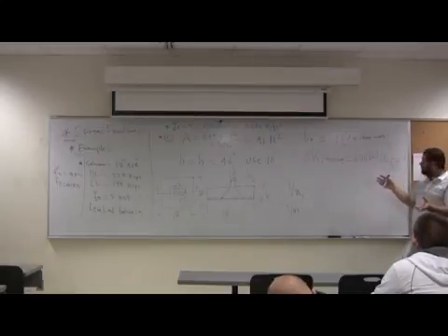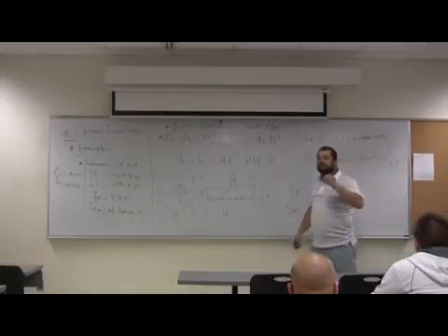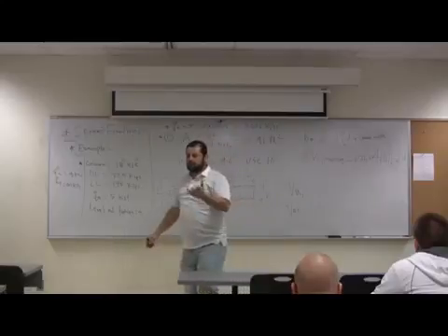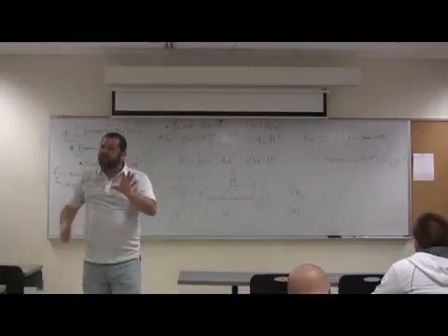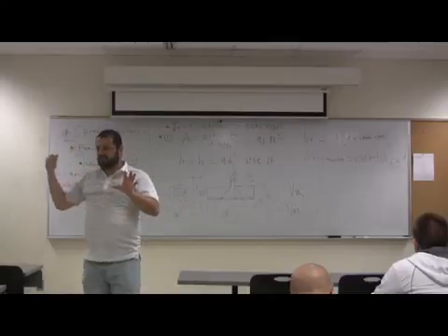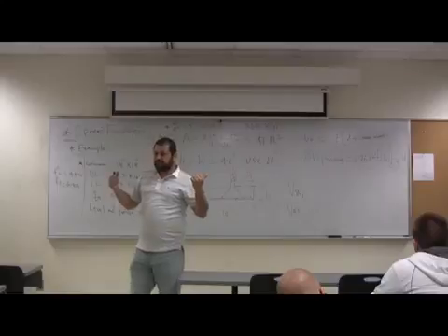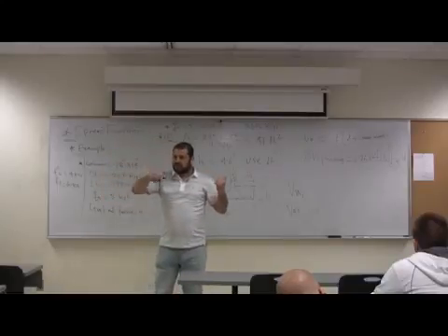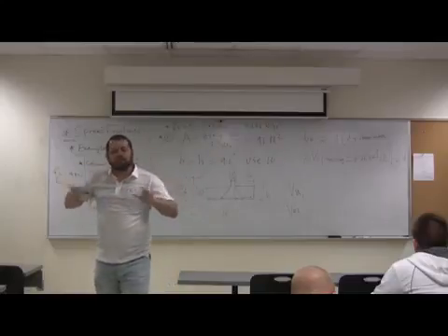So we're going to assume D, calculate this, compare it with that. In single footings, punching shear controls, so you determine D based on punching. You check the one-way shear, and usually it's good. In the combined footing, one-way shear or the beam shear controls the design. The punching doesn't control the design. In the wall footing, no punching.